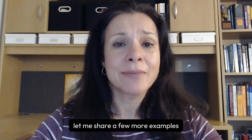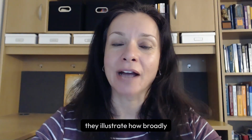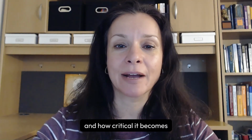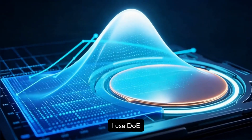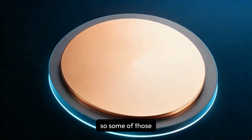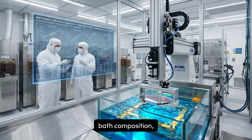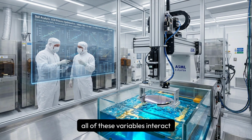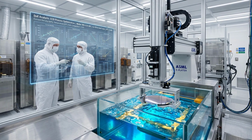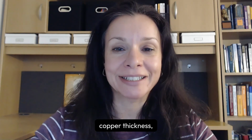Let me share a few more examples from my pharmaceutical and semiconductor years, because I think they illustrate how broadly DOE applies and how critical it becomes when the stakes are high. In semiconductor manufacturing, I used DOE extensively for electroplating processes. Some of those inputs or variables were plating chemistry, plating speed, temperature, bath composition. All of these variables interact in a way that affects the outputs, which in this case were copper thickness, uniformity,